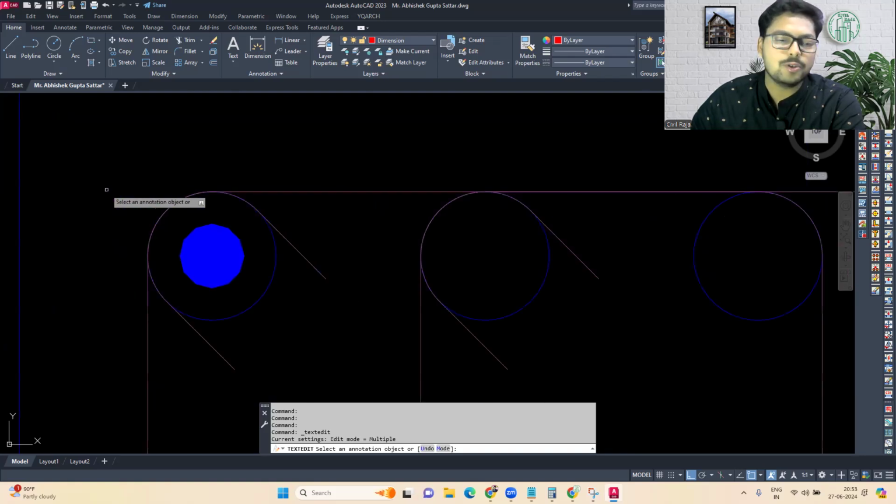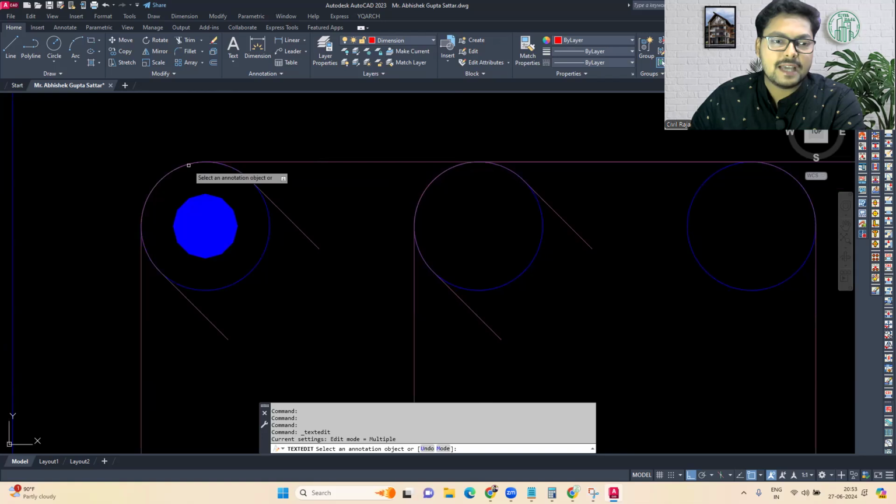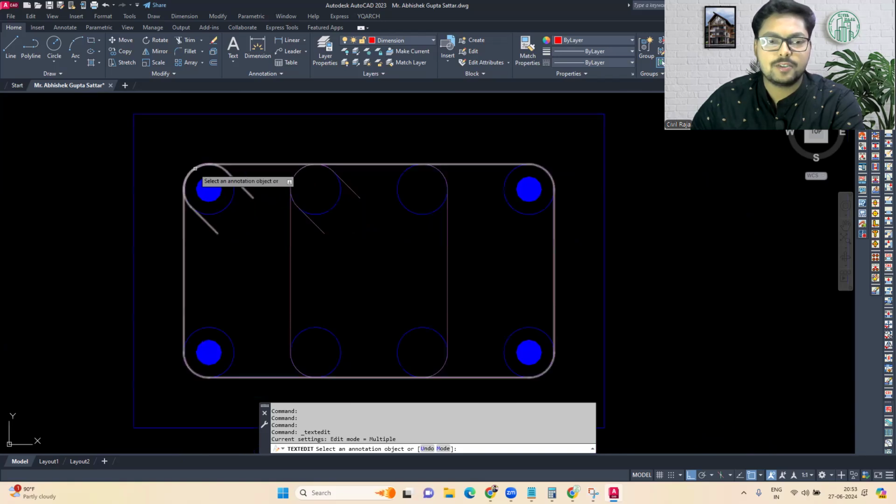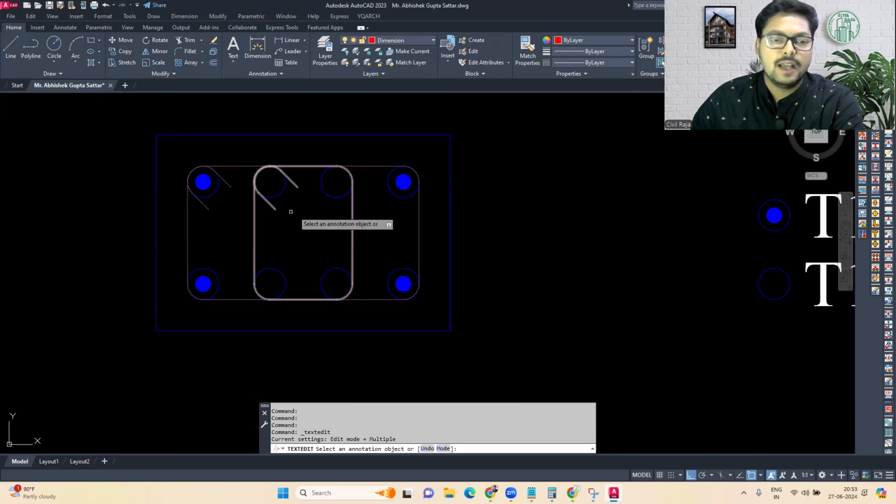In most cases, you will see that these ties are bent up for 90 degrees. So 90 degrees is a very wrong provision to do. We have to always bend the ties at 135 degrees, from both the ends. So it should be bent at 135 degrees, and then we can use this arrangement also.